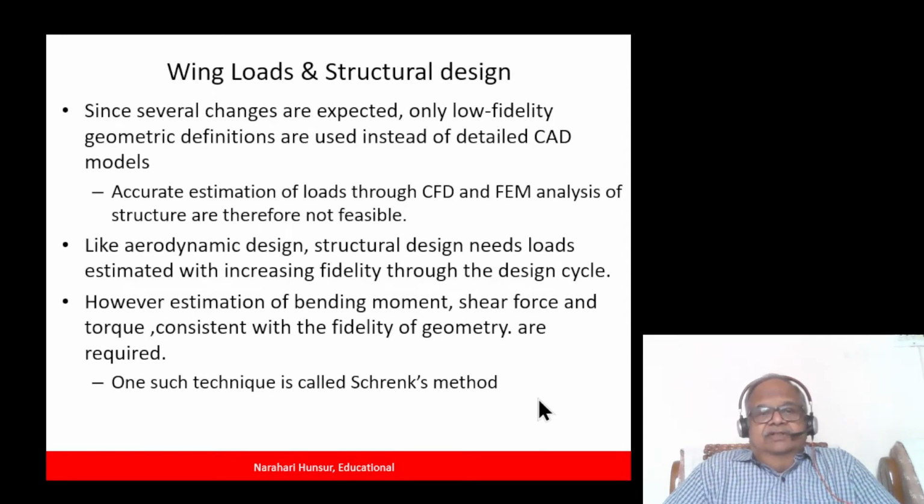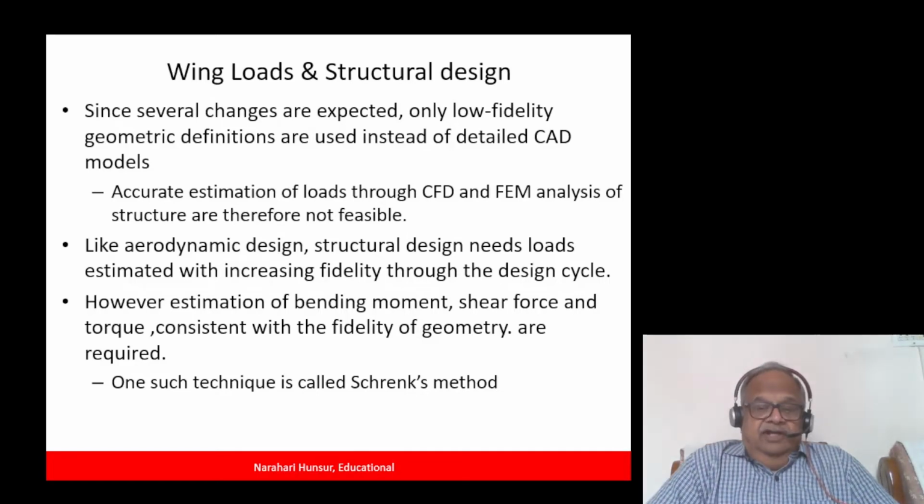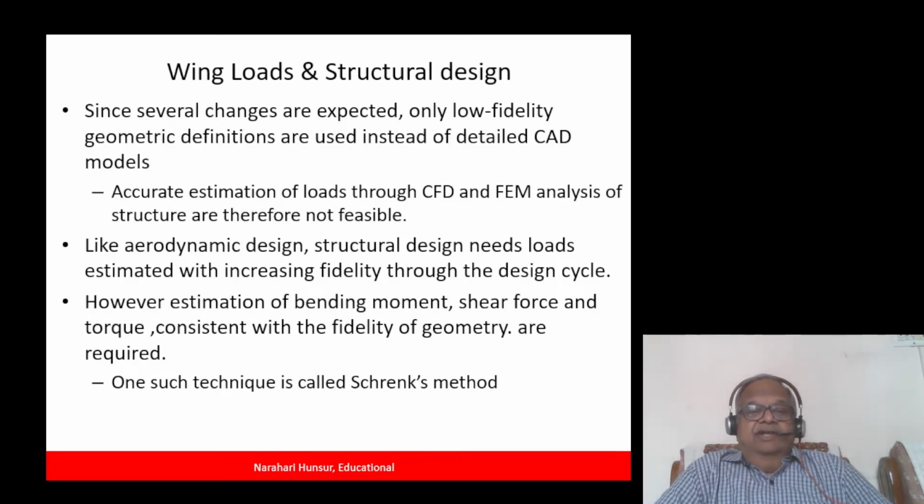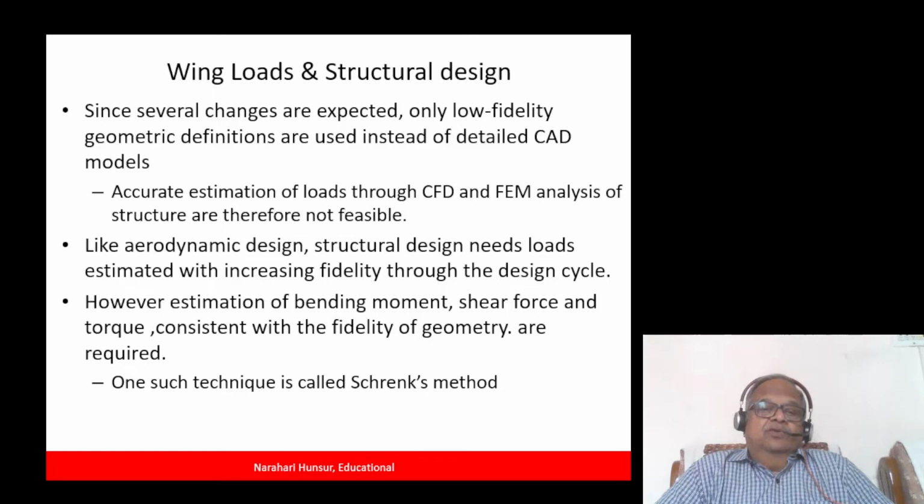Since several changes are expected, as mentioned earlier, only low fidelity geometric definitions are used instead of detailed CAD models. What I mean by low fidelity is, airfoil definitions are given for a chord length of 1 meter. So I decide on the planform and then scale the airfoil at the local chords, and then loft it into a simple surface. It's not the same high fidelity surface as you get in CATIA or AutoCAD or any one of those CAD surfaces, but enough to be able to run the low fidelity aerodynamics code which we were using earlier.